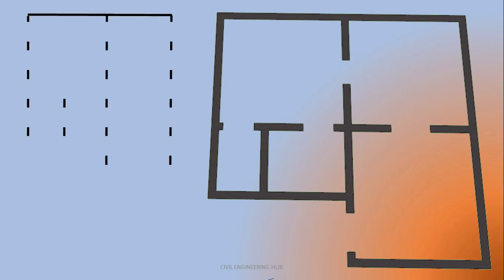This plan is a very good example of selecting long wall and short wall. In this plan you can fix any direction, either horizontal or vertical, as a long wall or short wall. To solve this kind of plan, the first and very basic step, whatever the plan is given to you, is to first draw a one line diagram of the entire structure, which will help you to understand easily how to divide the structure.